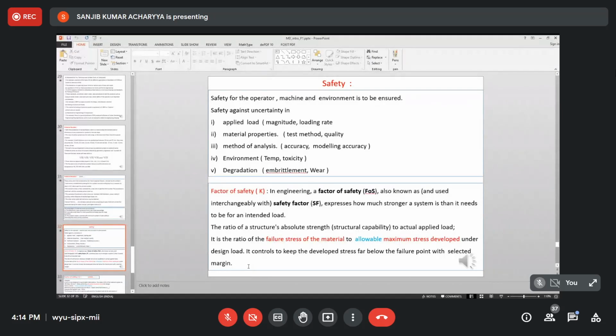Yes, sir. Now, degree of safety can be quantified by factor of safety. If somebody specifies that though the material can sustain 1000 kg load from analysis, it will allow only 700 kg, what is the margin of safety? 1000 by 700, 1.3 or something like that. Is it? Yes, sir. But while designing, the designer used the factor of safety in a reverse way.